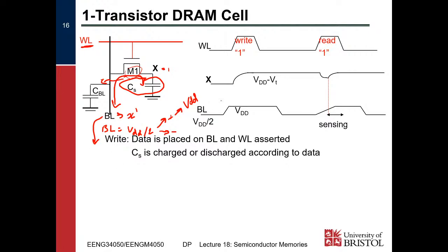So what you would have is all these cells tightly packed in an array, and then you'd have some processor which is reading out of that array of data because it needs some particular part of it. So what we do is we store it like this. We have this complicated read procedure, but it then gets sensed by some sense amplifiers, and then it goes into your logic because that restores it to a full swing 1 or 0.